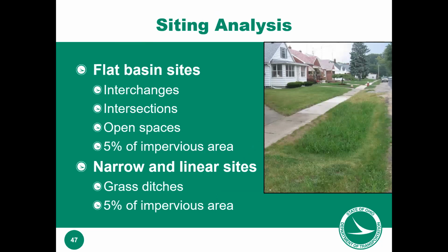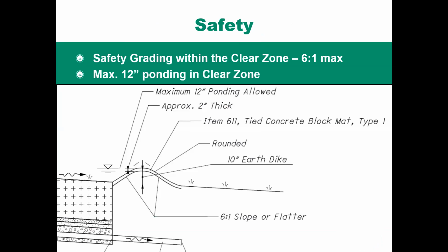They can fit in a lot of times in interchanges and intersections, more like a site development, or in a linear area. This bioretention cell you can barely see here on the right side is just that thicker grass right off the road. So it's a real small one, but they fit in a lot of places. And they're pretty easy to get a rule of thumb on how big they are, because generally your bioretention cells are 5% of the impervious area. So they're not small, but 5% of your roadway area might be only 2 feet, 3 feet wide along your whole roadway. So then it really is just like a ditch where you dig out and put your bioretention, your sandy soil in, and they can fit in a lot of places.